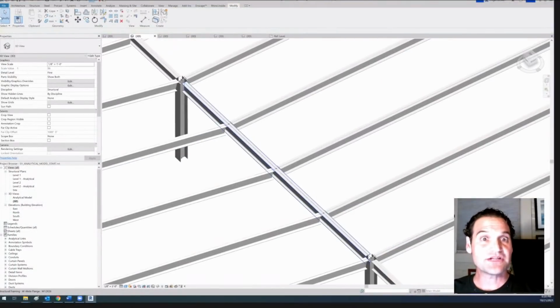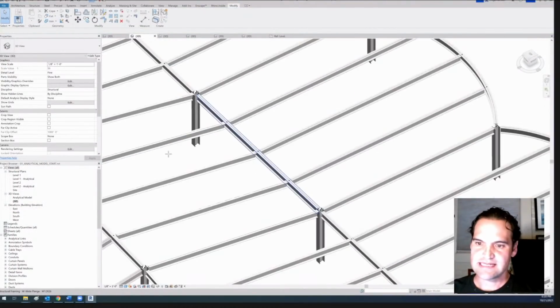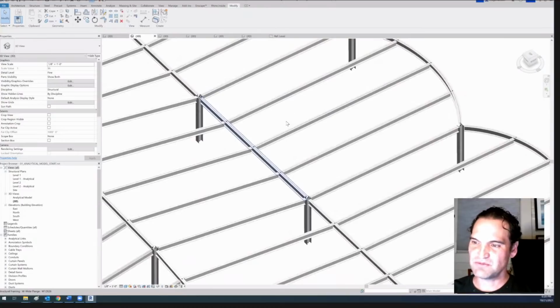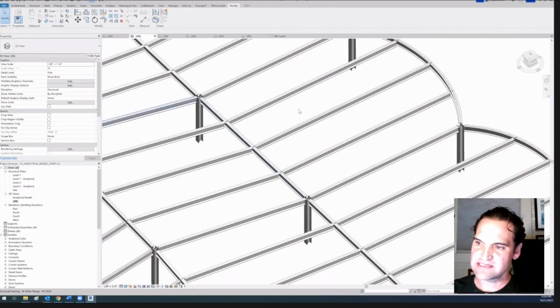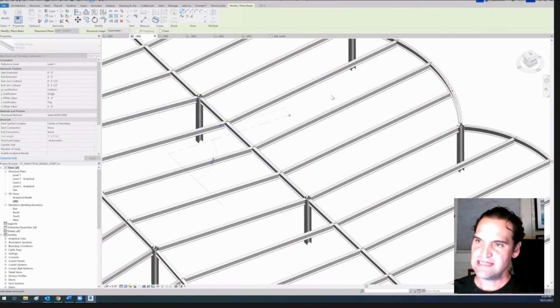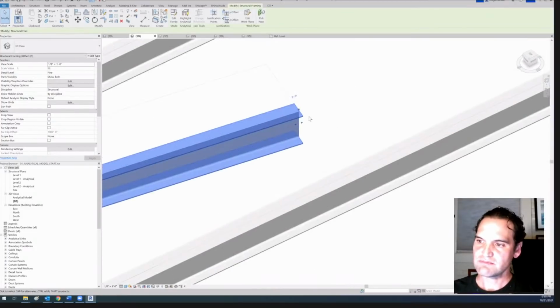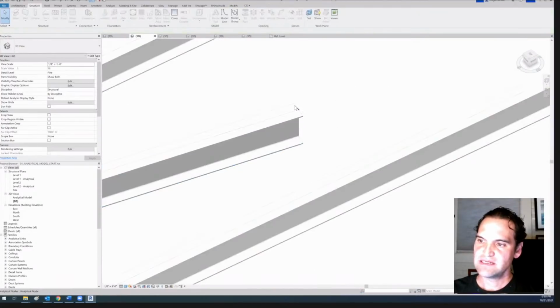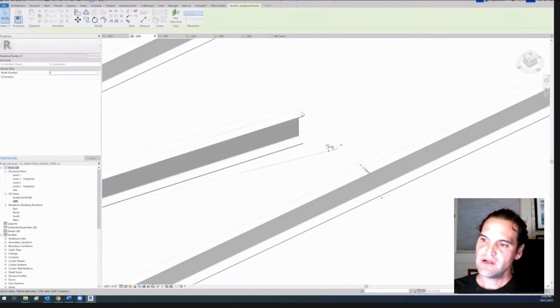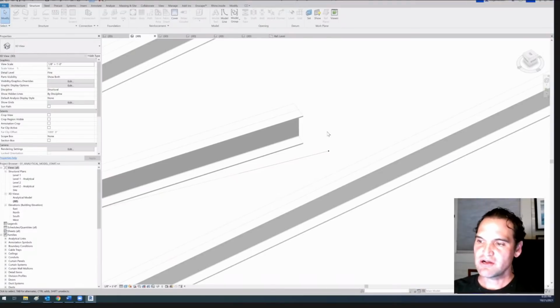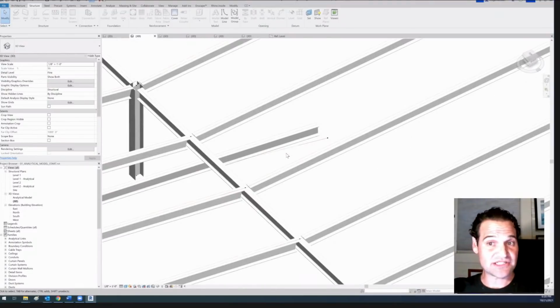That's the nature of an analytical model: if you build a physical model, the analytical line is always built with it. However, in the analytical adjust world, you have the ability to shift and move it around relative to the beam. They are, quote unquote, still associated through the API, but you have the ability to do that. Why do you do that?